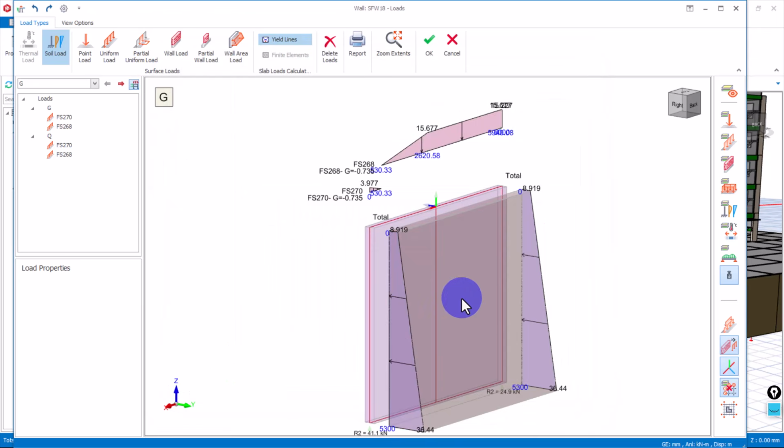So in that course, I can see that our soil load has now been added to this particular wall. I'll then come again and click on OK here. Now on clicking on OK, I'll wait for that to finish up. Once it is done, we will then go and copy that wall load and paste on all other basement walls instead of doing them one after the other. Okay, that is fine. So wait for that to just paste right now, and then we'll proceed to the next step.